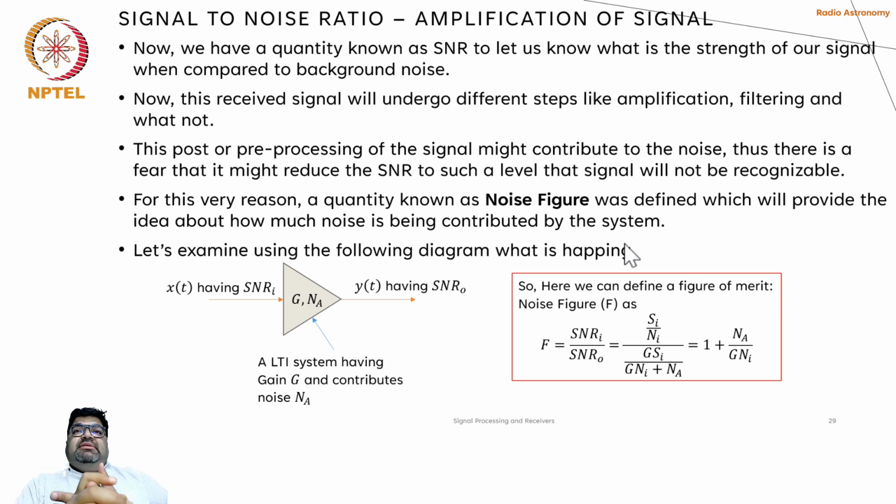So the desirable thing is that the system itself should be at a lower noise temperature. Sometimes that is ensured by putting the system inside cryogenic devices, because thermal noise is the major part of the system noise itself, and if the temperature is maintained at a lower ambient temperature, then the system noise contribution can be lowered.